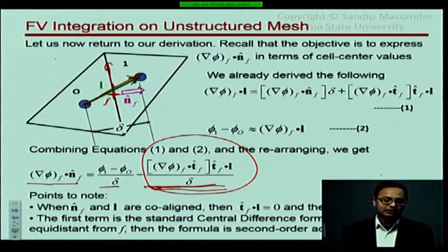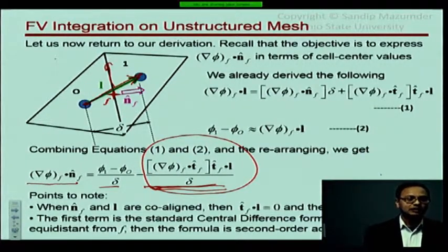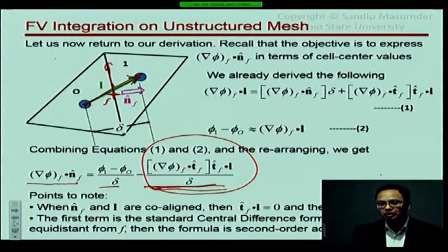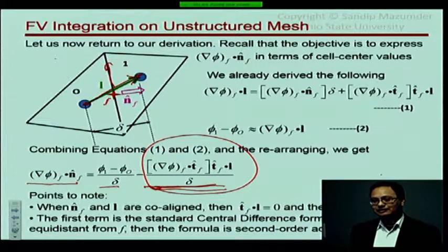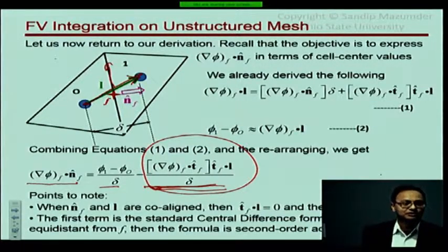If your mesh generator is producing a bad mesh, you'll get poor convergence. As a user, you are much better off spending a lot of time getting a good mesh, spend a couple of days getting a good mesh and then running your cases, rather than having a poor mesh and your code taking days and days to converge, and sometimes convergence stalling. Okay? Even though it's tedious and it's really something we don't like to do, spending too much time on mesh generation, but that's the way it is.